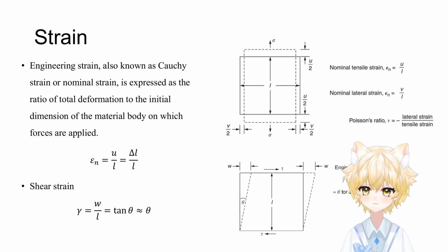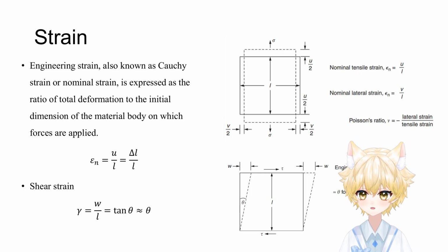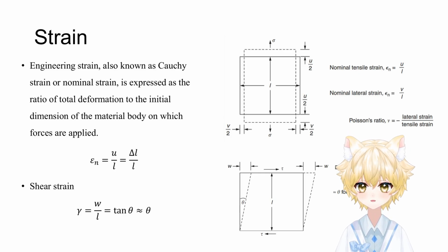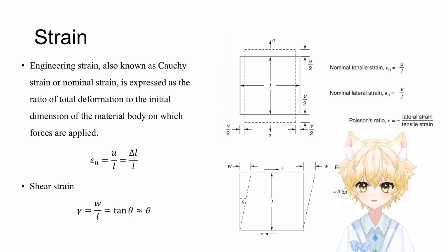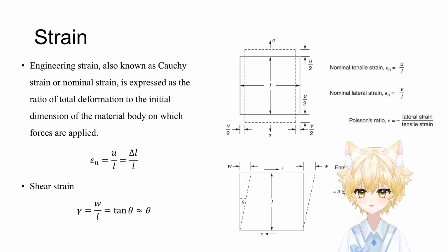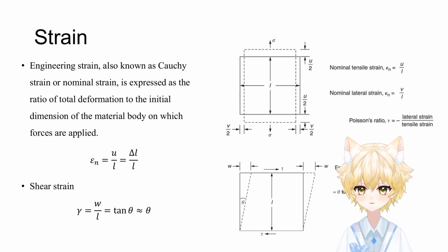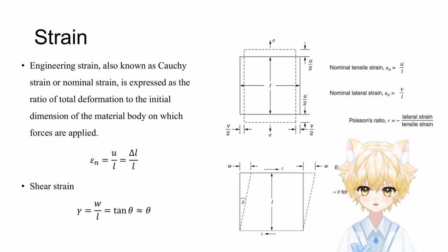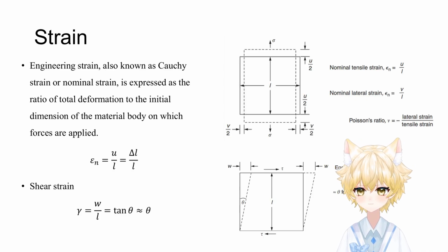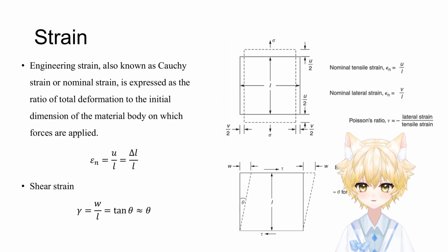Materials respond to stress by straining. Under a given stress, a stiff material, for example steel, strains only slightly. A floppy material strains much more. The modulus of the material describes this property, but before we can measure it or even define it, we must define strain properly. The kind of stress that we call a tensile stress induces a tensile strain.